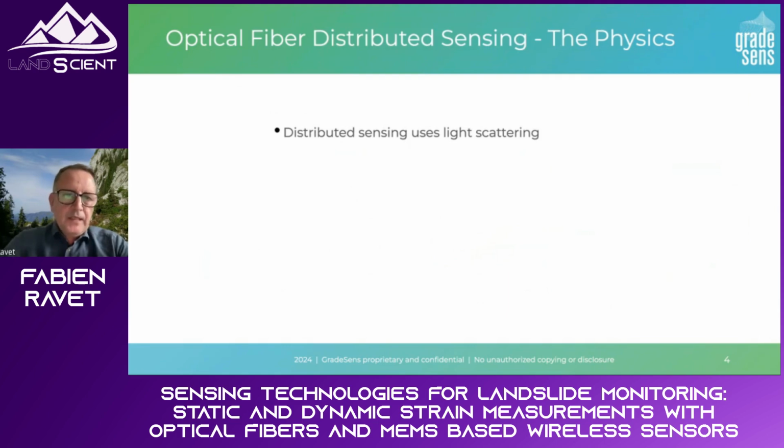If we talk about optical fibers, the physical mechanism behind sensing is light scattering, and light scattering is natural. As soon as you have light, as soon as you have a medium, you will have scattering. There is no way to avoid it. And actually, light scattering for telecommunication is an impairment. But for sensing people, it's a very good friend. We will see why. Scattering is natural because it comes from the inhomogeneities in silica, which can be static or dynamic, moving or vibrating.